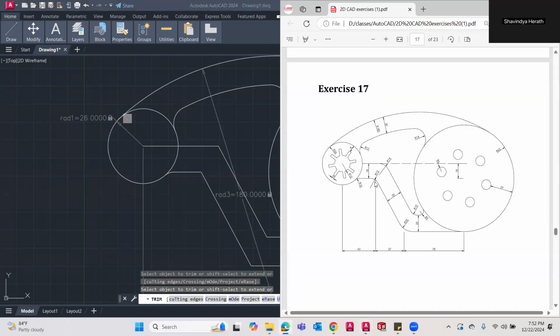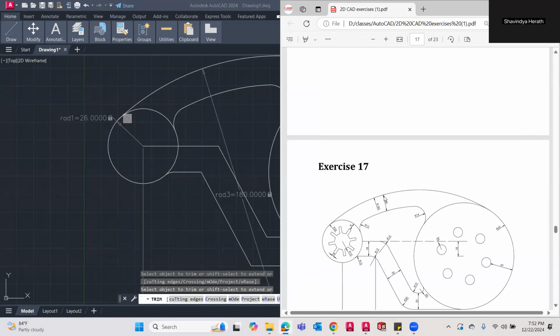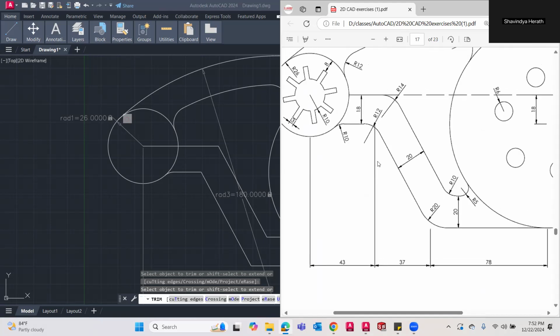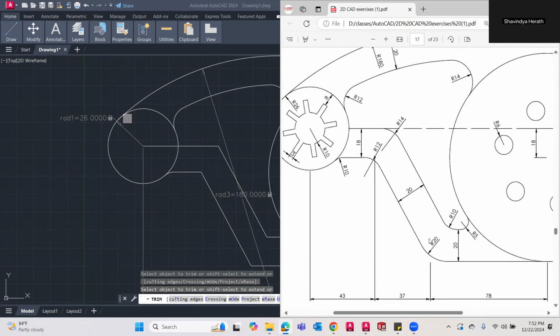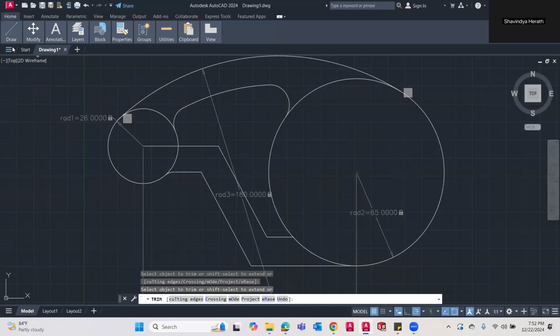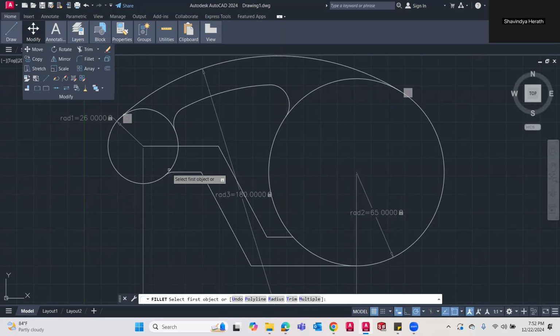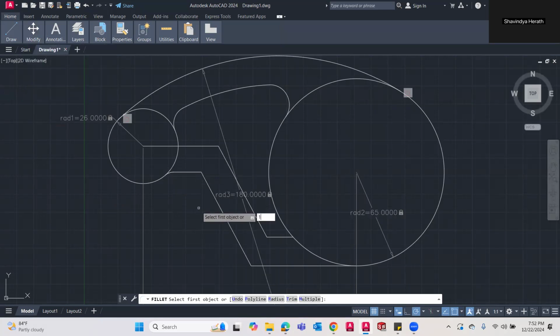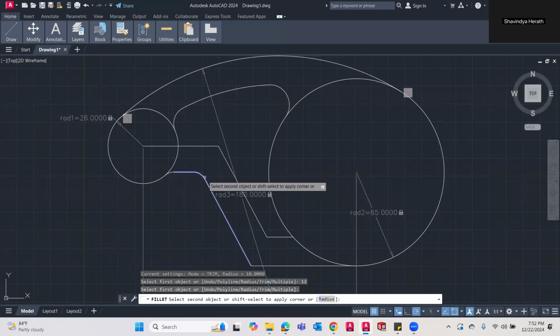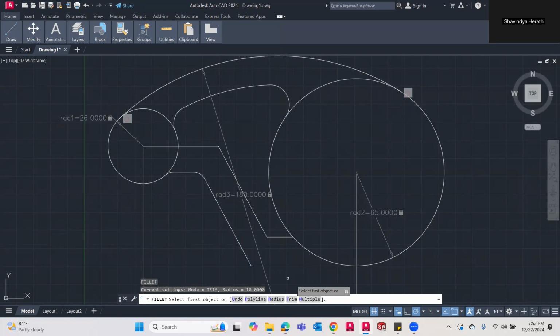these two parts, right? All these fillets, right? So first two fillets are radius 12 and radius 20. Right? Go to modify tools and then radius is 12 and press enter in between these two, and again radius is 20 and press enter in between these two. Right?